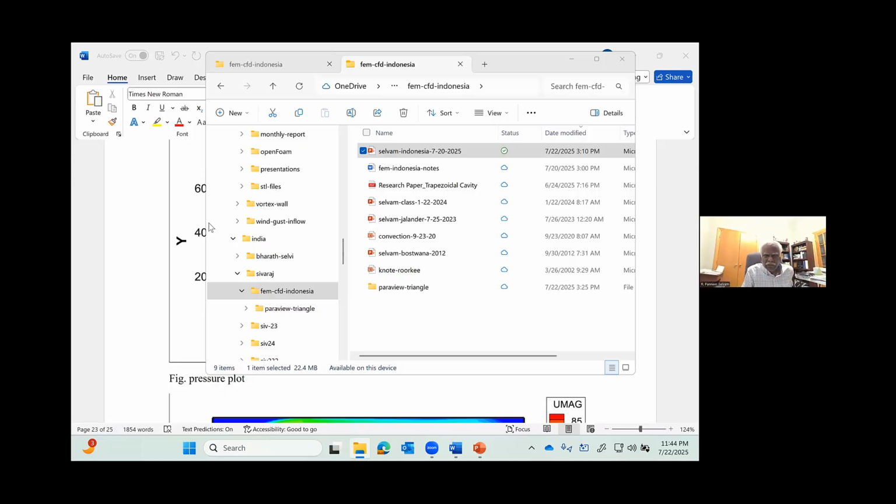Let me see, there is some more there. Professor, please, can you show the governing equation which you solved and got these results? I think these are all incompressible flow. So the equation, I put it in. Only thing is the last one I showed, because it's a high Reynolds number flow, I also used large eddy simulation, turbulence and other things. But if you read my book and other places, you can get to know more. But the governing equations are same, incompressible flow. Only thing is you have some modification to include the turbulence effect.